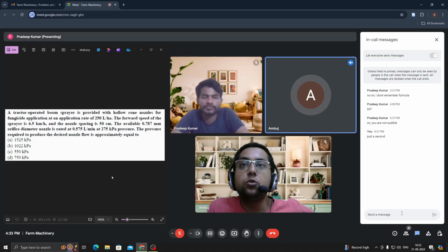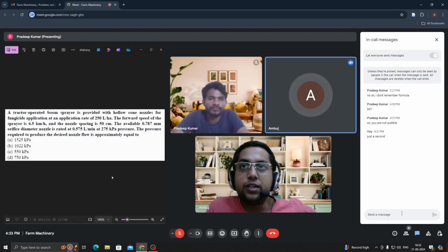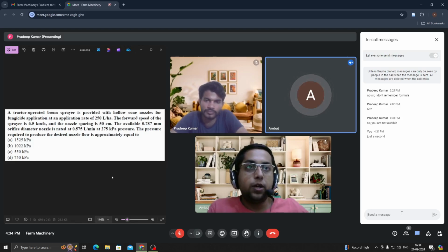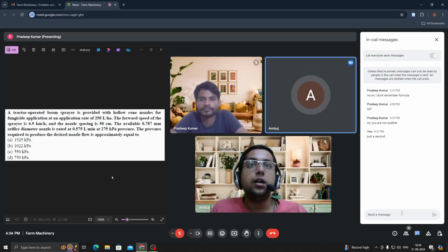In this particular question, first you have to calculate the discharge rate. What is the discharge rate in liters per minute? This is a two-step question. I am telling you the approach, you just try to follow. First thing is Q directly proportional to root of P that we will use. Another thing is first you will calculate the discharge rate which is required.